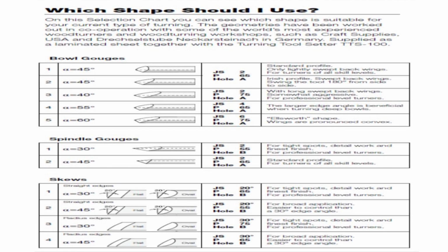The key as you go through these, as we talked about earlier, is that you want it consistent. You want the profile on the sides to match one another. You don't want one side different than the other. You want that symmetry there, and you want to keep that edge convex. You want it up. You don't want to dip in there, because if you get that dip, then you've got sharp edges that are going to catch as you begin to turn.